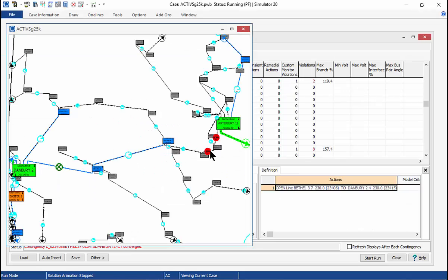And again, that's one of the lines in here that's overloaded, this one right here. So they're kind of in series, even though there's another station right here that feeds in. But the flow on one heavily depends on the flow on another. So we're going to just set up our remedial action scheme to look at the flow on this first one right here.